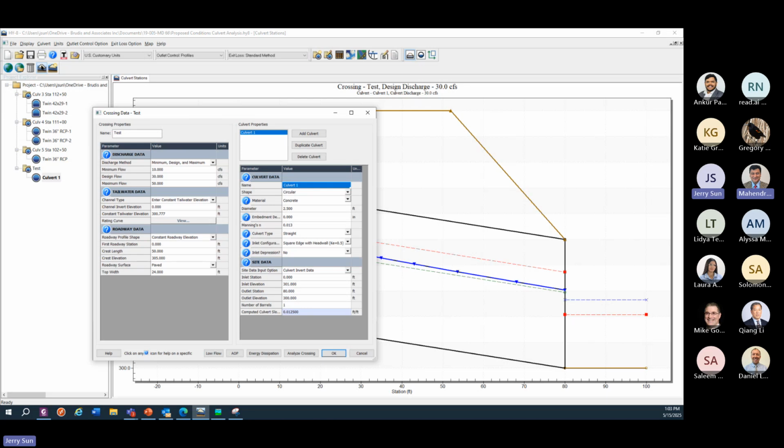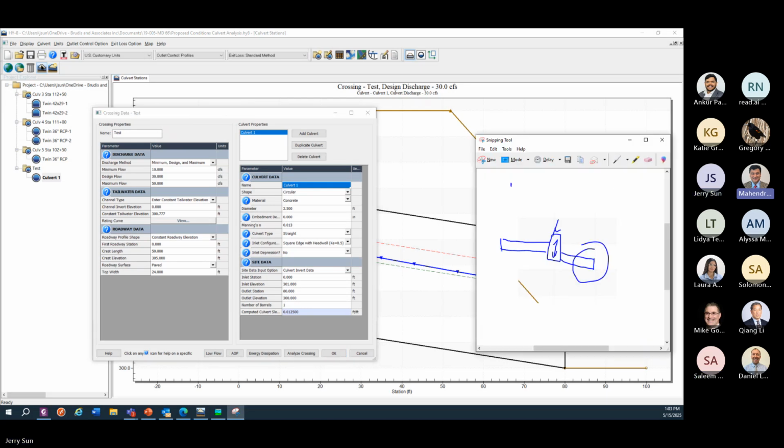Yeah. Generally people get confused about how to take it, so very quick. On the left side, this is y, this is x. When we take a point, this is the first point, second point, third point, and then we give the station and elevation, starting from zero. That's everybody's knowledge. So let's stop there. For example, 0 to 20 feet, you get a point, and they come out as a cross section like this. This is very important in the HEC-RAS.